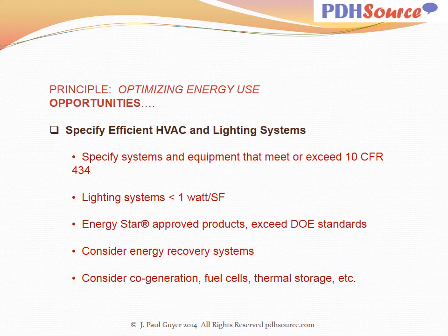Now, an area where there has been very substantial improvement made in the last 2 or 3 decades is in the industry that provides the equipment and the energy consuming products that go into buildings, like as an example, artificial illumination. Well, not too many years ago, the rule of thumb for energy consumption in a typical office environment for the lighting was around 2.5 watts per square foot.